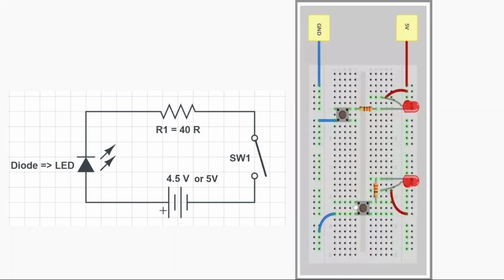Again, it doesn't matter even if they're connected or not. But the thing is, the plus side, as you can see here, this is the plus side of the LEDs coming to the plus supply voltage, where we will be connecting the plus 5 volts. The negative is connected to the resistor, and the resistor leg is coming to one of the switch terminals.